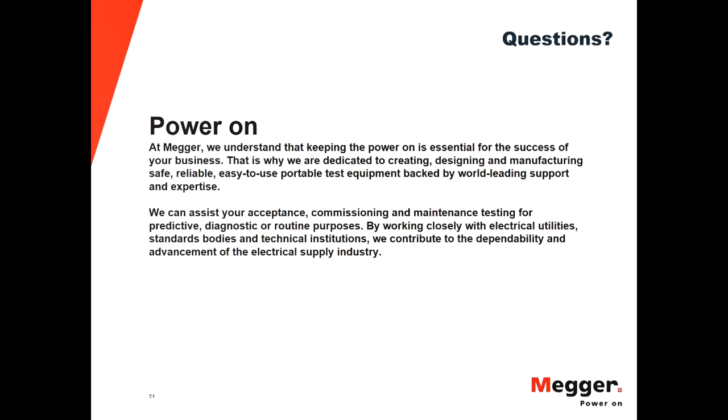Do not go beyond the minimum voltage or the end voltage, and by following the testing schedule that we mentioned, every 25% at least, you're not testing the battery so often that you're going to be taking too many cycles. So in the end, it's like any other test in the electrical world: if you don't use it correctly, you can destroy the equipment. But if you use it correctly, it's going to be a safe test, and it's not going to be affecting your battery. All right, the next question.